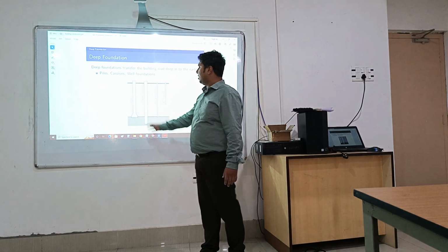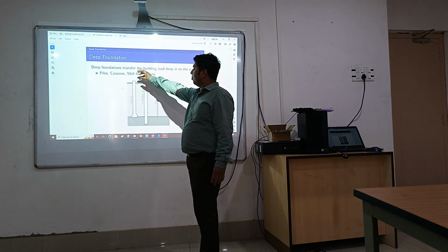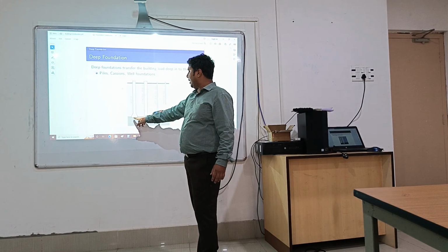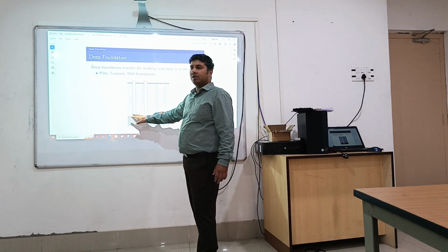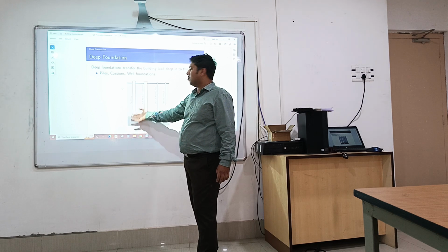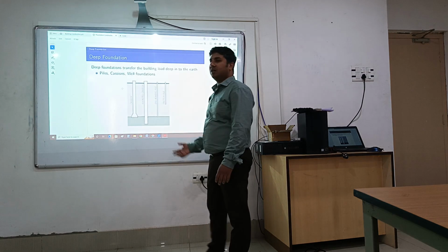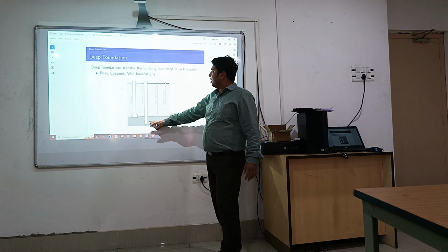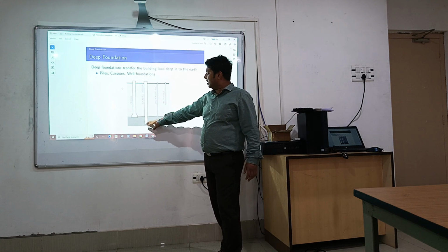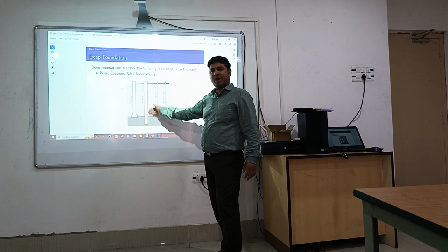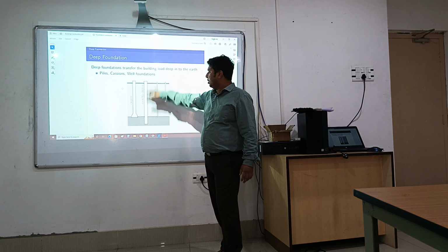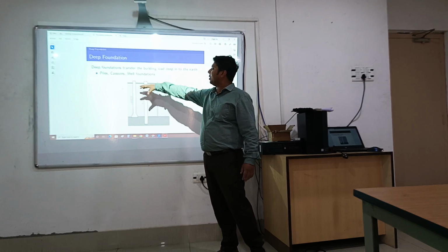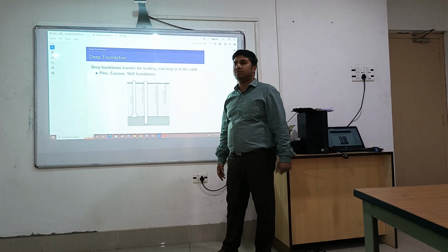In caisson footing, it is more hollow and more spread, and here it may go beyond near your hard strata, where the load is taken by the end bearing. In a socketed caisson, even if the drill has reached the hard strata, it may go much beyond, and due to the end bearing where there is more spread, the caisson is able to take more load.